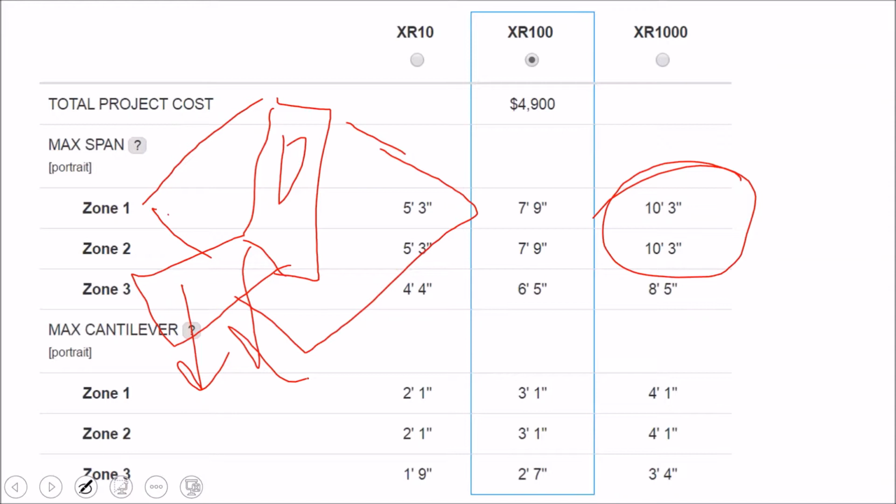What leaks are pre-existing attachments that have been on the rooftop for a decade, like a plumbing vent or a skylight. As the solar installers are up on the roof walking around those pre-existing penetrations, they're weakening the attachment point, and maybe the sealant around the flashing has dried out and become brittle, and all the tromping around on the rooftop busts it up and water can get into it.